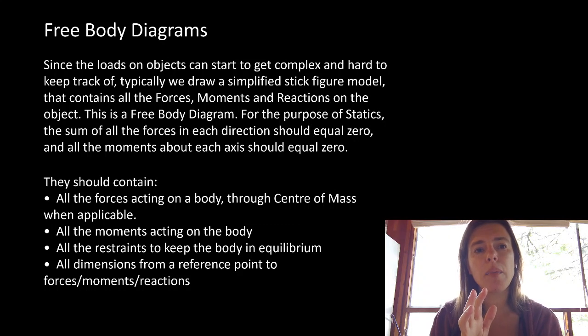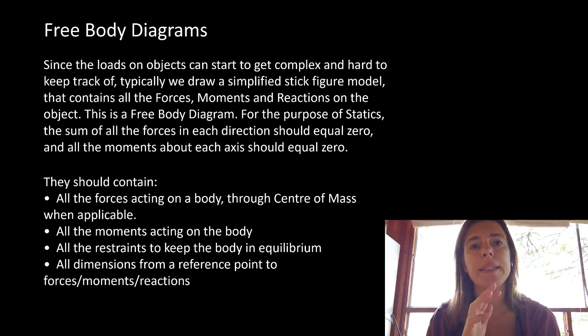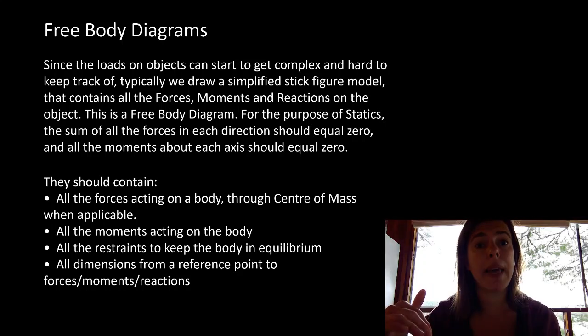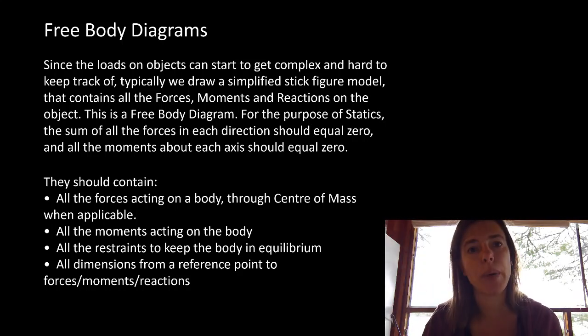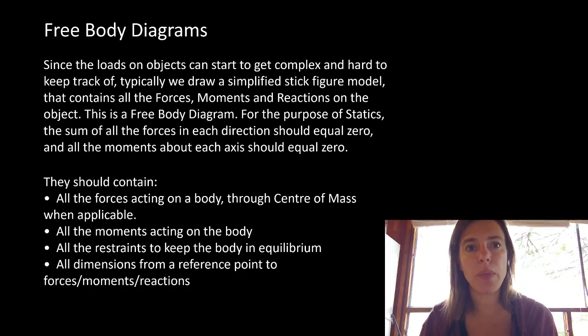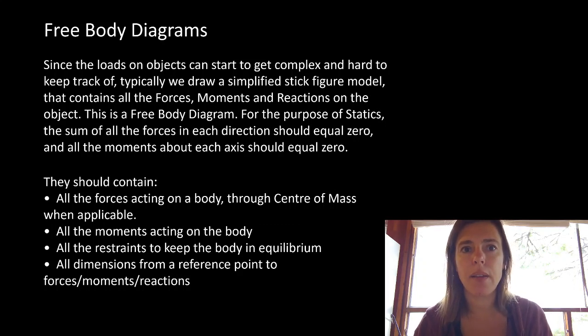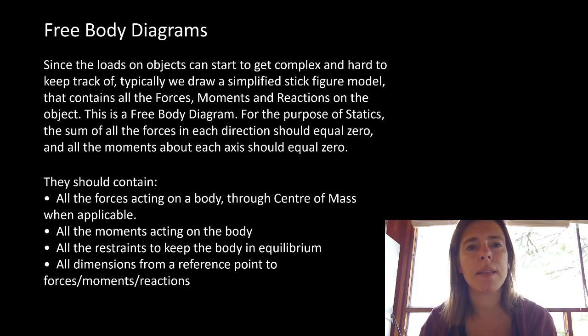We often find that a little bit overwhelming, and quite often we'll break it down into a 2D world just because it's easier to get our head around it, understanding that there's depth to the system. Sometimes what we'll do is solve the problem on all three planes if we need to, but often just breaking it down into a 2D plane solves all of the loads that we need to think about. We can often get away by doing it in a very simplistic 2D way. If it's a bigger system, sometimes it needs to be a bit more complex than that, but often drawing one 2D plane free body diagram will get us all the things we need.